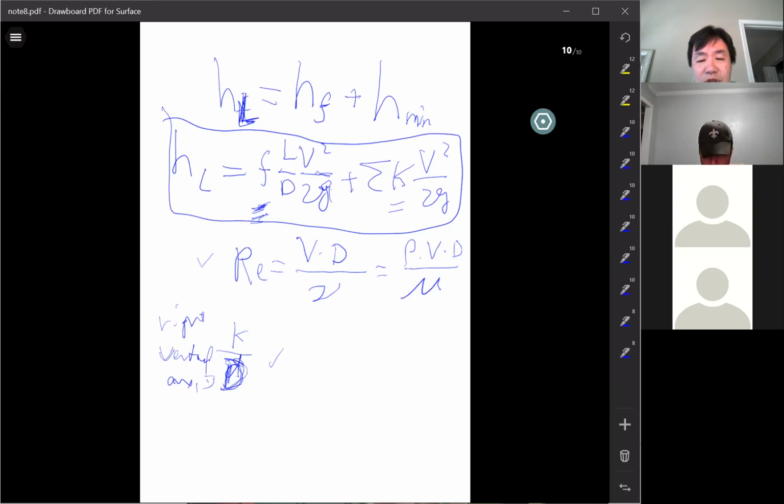So when you use the Moody diagram, first find your surface roughness, then pick the blue curve that represents it. What about in between? If your roughness is in between two curves, that's fine. You can interpolate a curve. So find the blue curve first using your relative roughness.